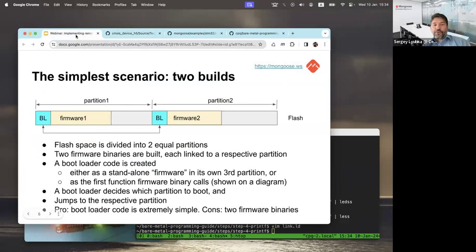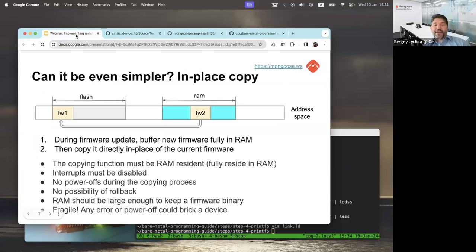What I want you to understand after this is how exactly we can put a function in memory, what the mechanism is, and how linker scripts are used for that. And just one note about this: if you put a function in memory, that means all the functions that this function calls should also be in memory, right? Because otherwise there is no point. If that function in memory calls another function which is still in flash, it will crash anyway.